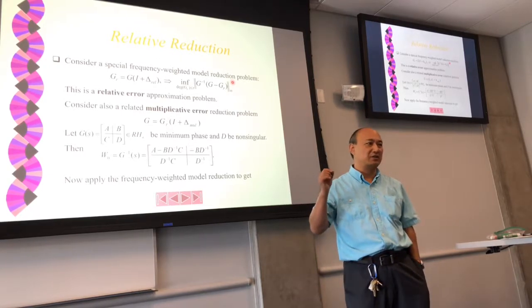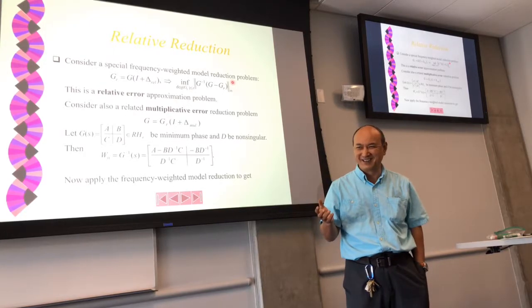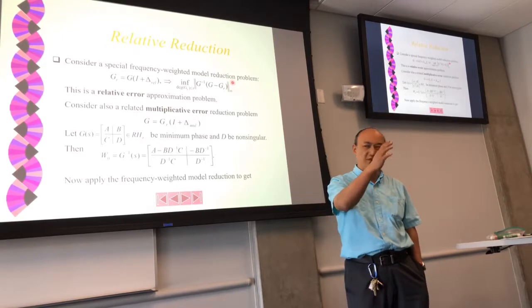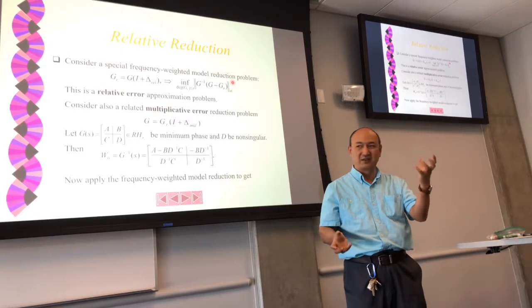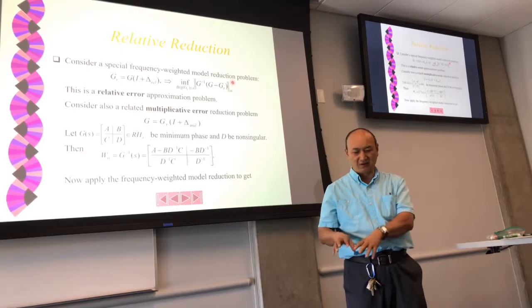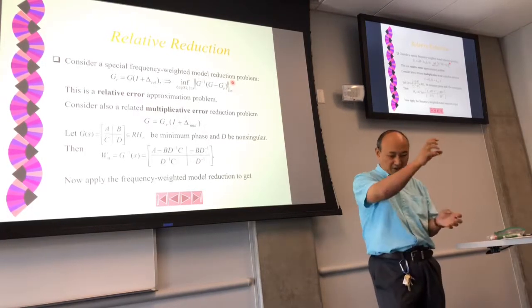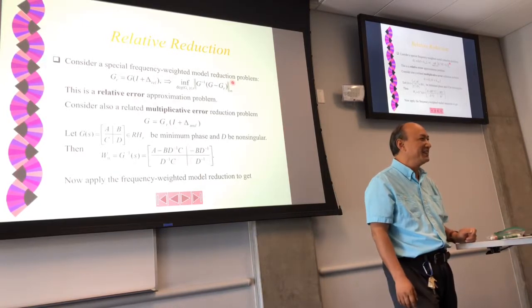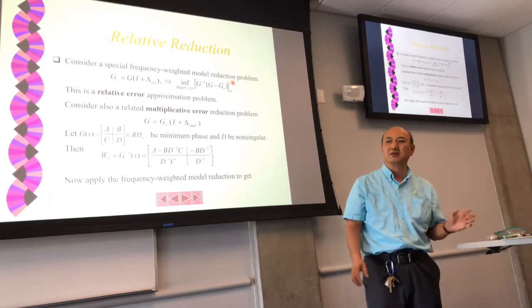There is a command to do the job automatically, just call hankelsv. It will give you all the ordered Hankel singular values. If you see the biggest one and the smallest one differ by like 2 orders of magnitude, you should consider truncating. But if they are all about the same size, probably you should not truncate. That will give you very good insight, to justify why you shouldn't use model reduction.